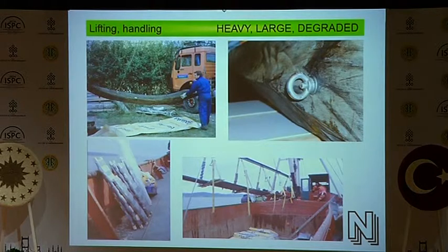The thing with heavy objects in particular is that one always has to think one or two steps ahead of what is going to happen next, because you cannot necessarily reuse the supporting planks. You need to have extra sets or things to put underneath, so you are always able to move it. So thinking ahead is a very good ability to have when you're dealing with such excavations.